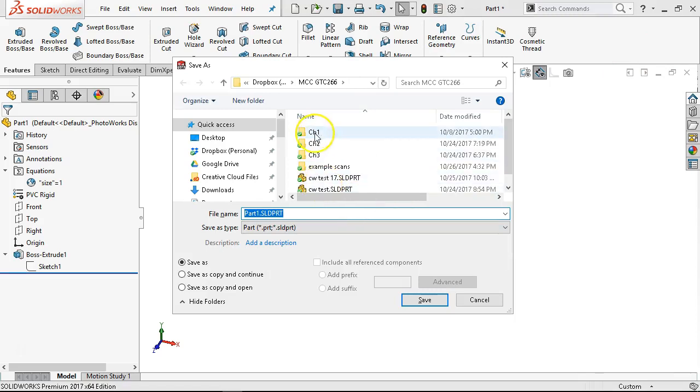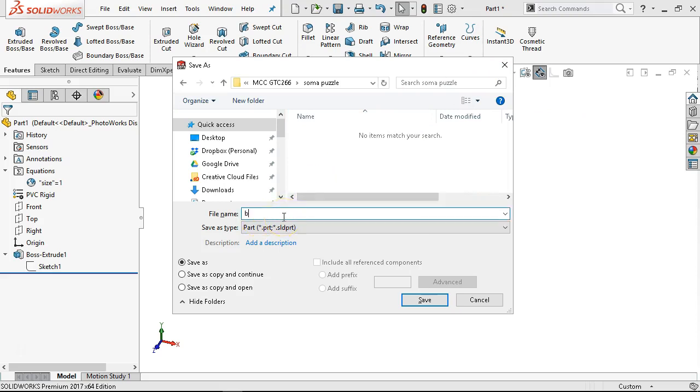And then we'll go ahead and save this. Let's go ahead and create a new folder. And this can be block. The names need to be of sufficient complexity that this will only ever be the only block, that I don't want it to be able to confuse, because SolidWorks sees the first block in the assembly and says that must be the one you want.